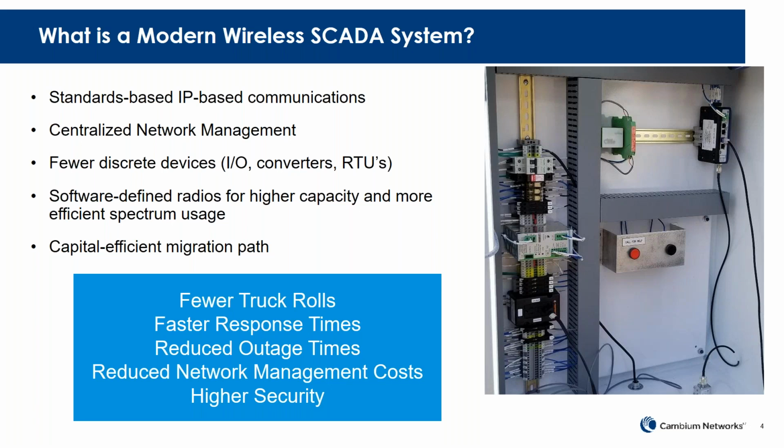The other thing you'll notice in here is that it is based on IP communication, so it's all standards-based IP. There's centralized network management, either via the GUI directly on the radio or, as I'll show you in a moment, a sneak peek at our cnMaestro support for cnReach. There are fewer discrete devices and a lot more integration with the cnReach radio. In this case, cnReach has built-in general purpose I/O, so the sensors are connected directly to the cnReach radio and can be read and monitored from the SCADA master back at the headquarters just using Modbus TCP.